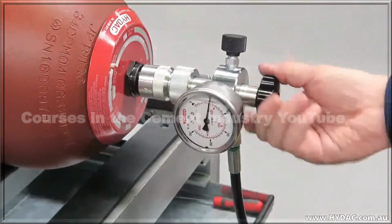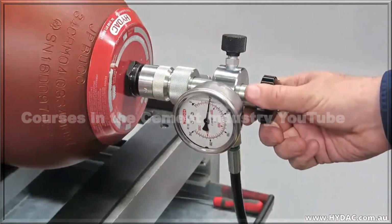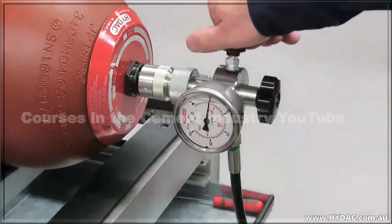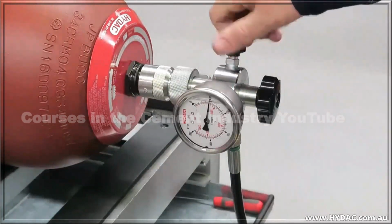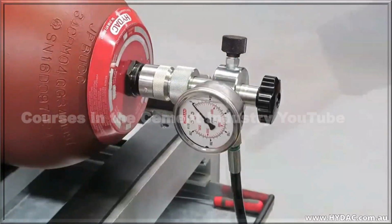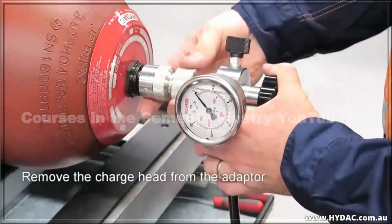Once the pressure is at the desired level, you can begin disconnection by winding the main spindle counterclockwise, then reclose the gas valve. The spindle has been fully wound back once a faint clicking noise is heard. Release the gas from the charge head and hose by opening the gas release valve in a counterclockwise direction. Once depressurized, you can remove the charge head from the A3 adapter.